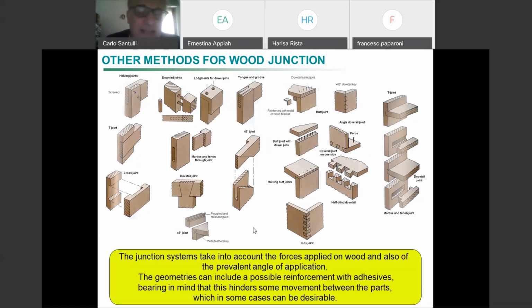When I talk, well, we have already talked a bit about metal matrix composites, so kind of aluminum particles or magnesium alloyed with magnesia particles. So we have a metal matrix. The matrix is the bulk of the material. Then there is a reinforcement or filler. The difference is not academic because a reinforcement reinforces, or I can have a filler that just modifies something else. For example, in polymers, I might have a filler, I might have calcium carbonate, which doesn't reinforce the polymer for the way I have to use the polymer for.